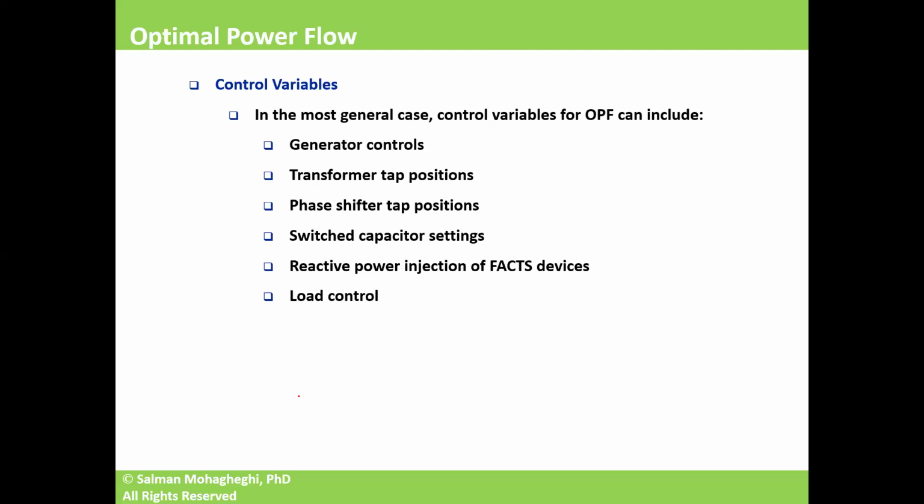First, we conduct unit commitment a day in advance to take into account the daily variations. Then we run multiple economic dispatch solutions to take into account the hourly variations. Then between those economic dispatch solutions, we run multiple OPFs or optimal power flows to reflect the minutely variations. And then we have AGC or automatic generation control that would take care of secondary variations in demand.